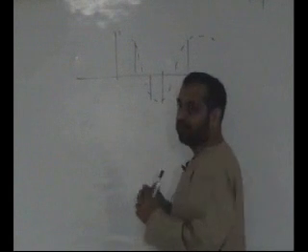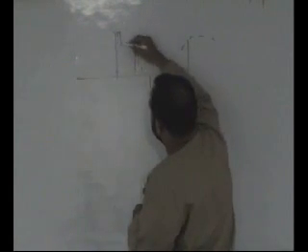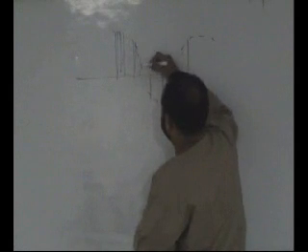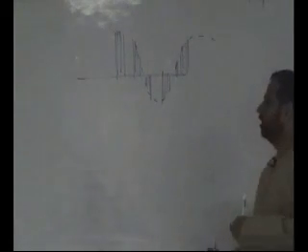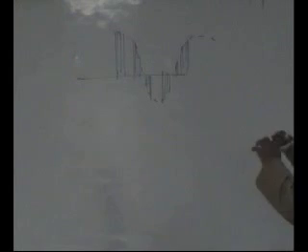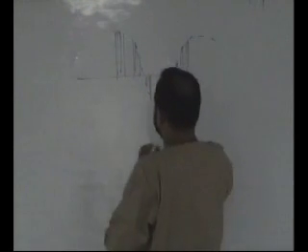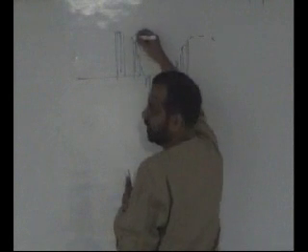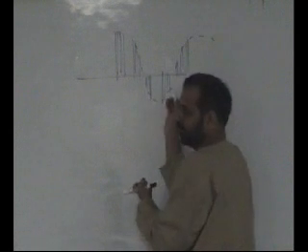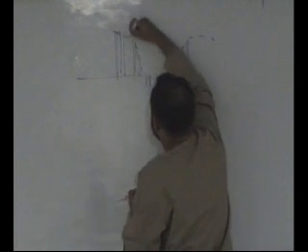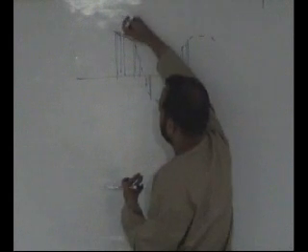But you have to interpolate to put these samples between two samples. So this is what is meant by bringing it up, that you have to insert so many samples to bring the sampling rate up. Obviously you have to use some algorithm to do that. A simple way is that you insert zeros, obviously that will change the shape of the signal. The other one is you stretch a straight line, this is a linear interpolator, and you add samples. Obviously this is also not correct because this is not a straight line.